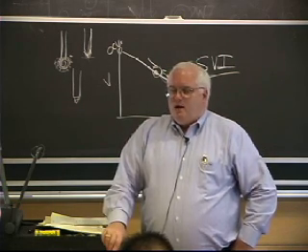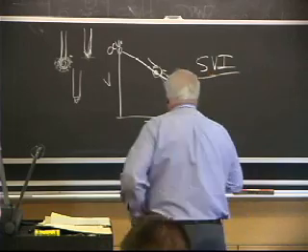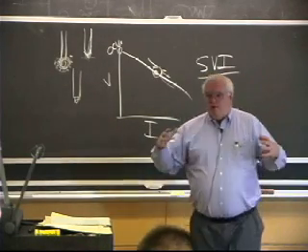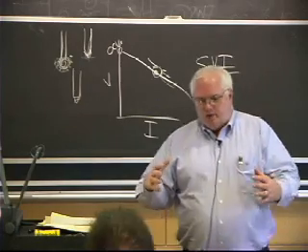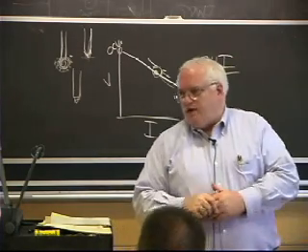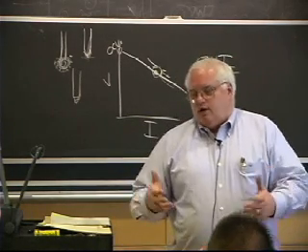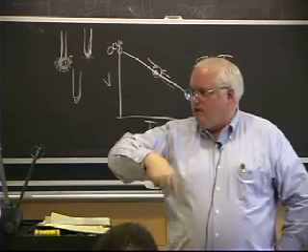Okay. Nowadays, now that we go to inverter power supplies, they have almost no inductance. There's no great big heavy inductor. I mean, the inductors in the old transformer regulator power supplies might have weighed 200 pounds of copper, because if you're talking a 500 amp power supply, you got to have some pretty heavy cable to make this magnetic field.